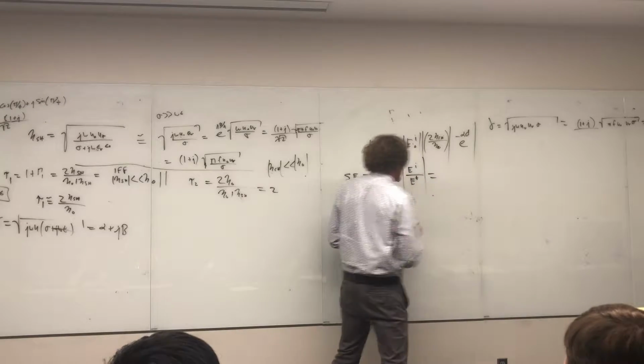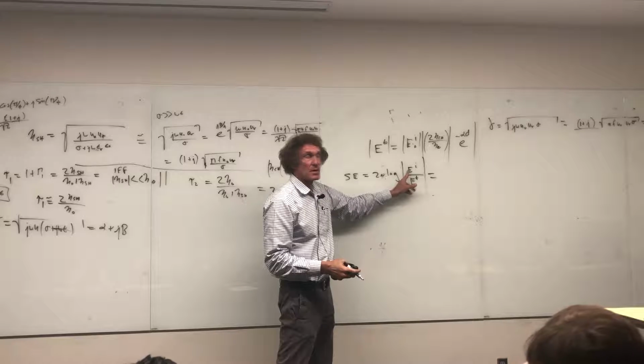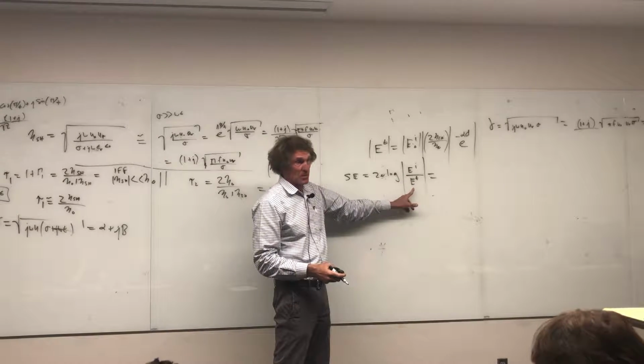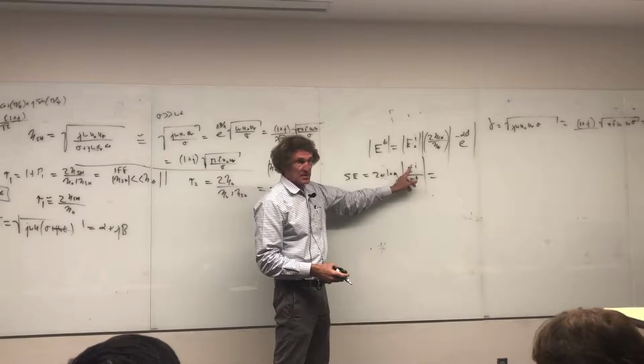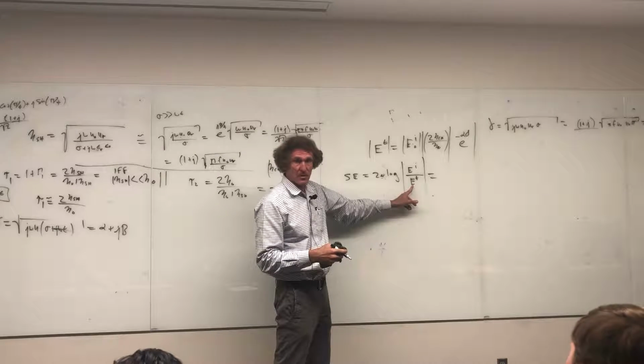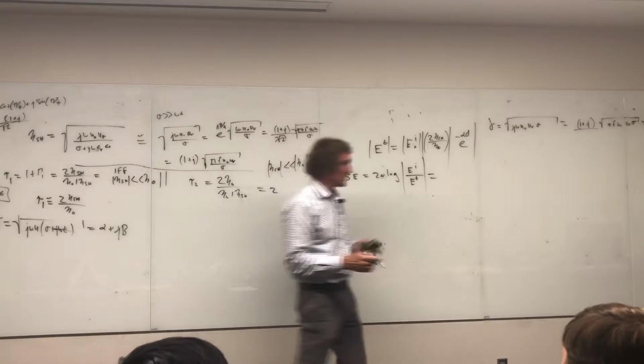Now here's what this comes out to be. Remember, this is a magnitude. We care not about phase. That's the incident field, whatever it was. That's the field that gets through the shield. So this is a lot smaller than this, hopefully, right? Means this is going to have a magnitude greater than 1, hopefully a whole lot greater than 1. And the log of that times 20 tells you the shielding effectiveness, how effective the shield is.